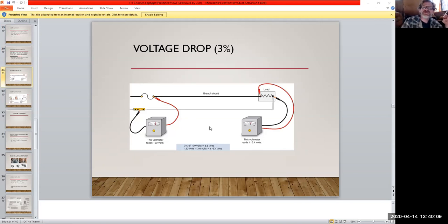That's why you got your meter. Your meter is your number one friend. You always have them. But you can even check that, like, let's say somebody had done work previously and didn't do the voltage drop formula, and the customer's calling up and saying, hey, I've got too little voltage. Well, you go out there, take a read on it with your voltmeter and go, oh, yeah, you're right.